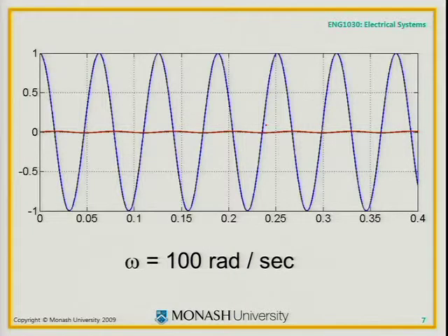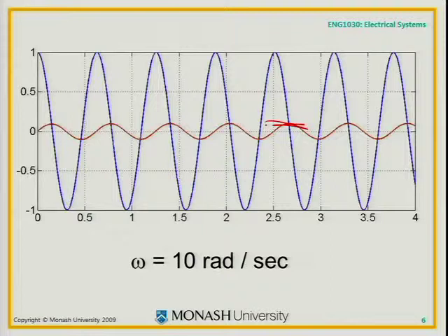If you want to make fancier ones so that, say, by 10 radians per second you were already zero, you're going to have to put in more capacitors or inductors. And so there's a whole field of filter design, which is about, well, how do I make something that passes these frequencies but blocks these ones? It's called the roll-off, how fast you start getting rid of frequencies.